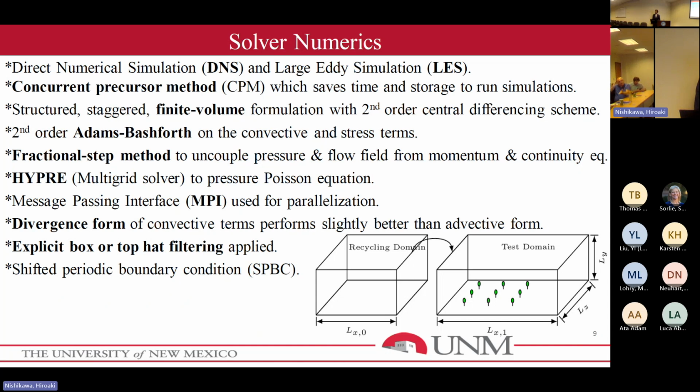But when the blade is curved, is your grid curved with the geometry, or is it still purely Cartesian? It's still Cartesian. Oh, you're talking about the wind farm turbine implementation. There are several ways you can imitate the turbines. One is called actuator disc. It imitates the thrust force on the Cartesian grid. We do not model the actual turbine structure, the details of the wind turbine.